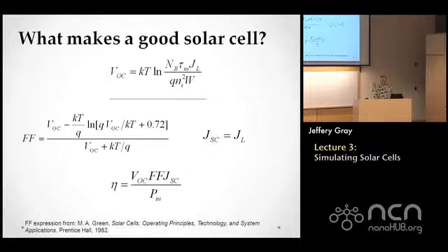And so with the open circuit voltage, short circuit current, and fill factor, you can calculate the efficiency of the device. But like I said, we're going to focus here on the open circuit voltage because that'll be the key thing. One thing you can maybe not see obviously here, but it's true, is that the higher the open circuit voltage, the higher the fill factor. So increasing the open circuit voltage is always good. And in this case, we're assuming that the short circuit current is basically just constant. So improving the open circuit voltage will automatically improve the fill factor. And that in combination will automatically improve the efficiency, which is obviously our ultimate goal. But we've broken it down to the key parameter, which is the open circuit voltage.